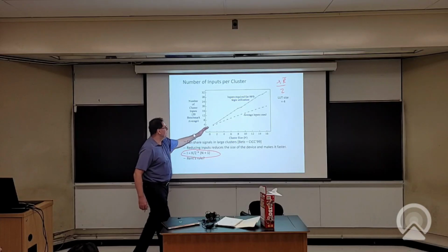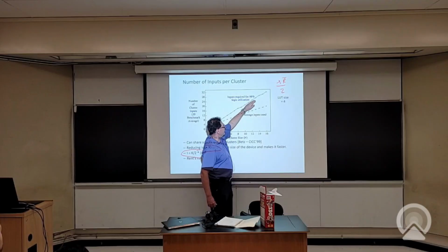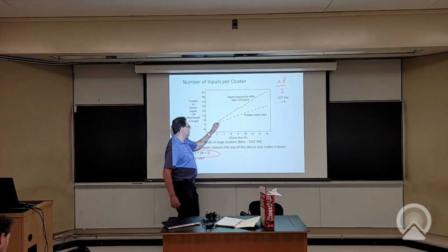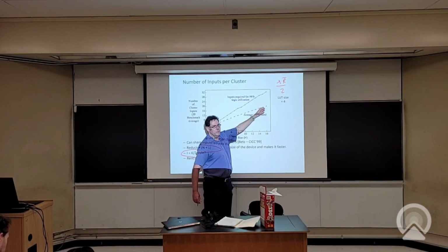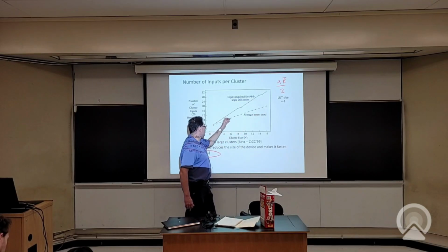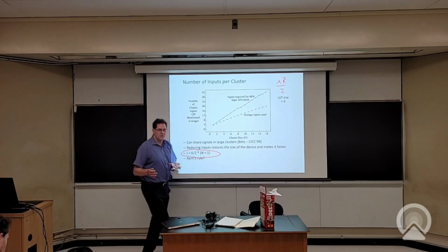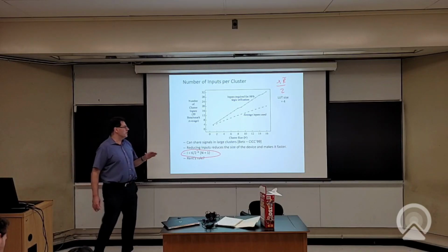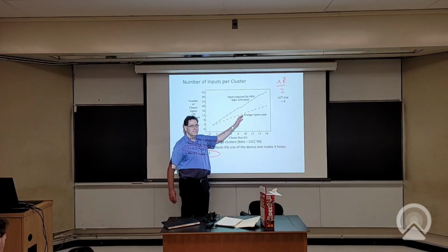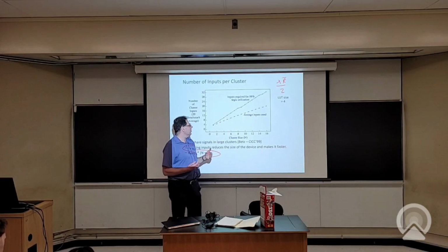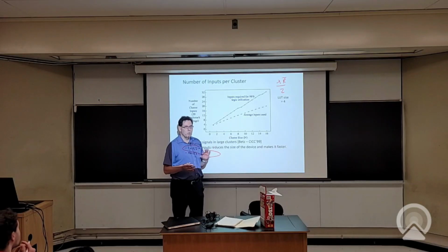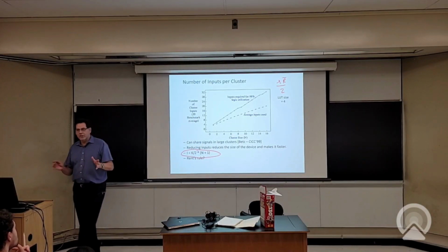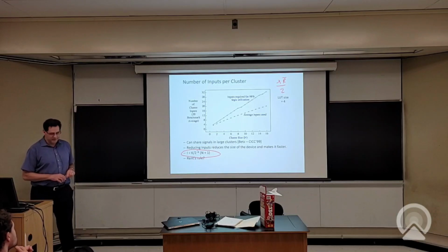So while the packer is clearly able to grab some related logic, it could probably do a bit better than this. And we can see that the curve is kind of flattening out, so it's maybe a little less than linear. But the other thing is the average inputs. Rent's rule predicts the average inputs, not the worst case. So if I look at this average inputs, it's somewhat more sublinear. So the Rent exponent is better. This also might mean there's some room for improvement in the packer they were using, right? Because in typical circuits, you should find a Rent exponent that's maybe more in the 0.5 to 0.7 range. So this looks a little high. So maybe there's some room for improvement in the packer.